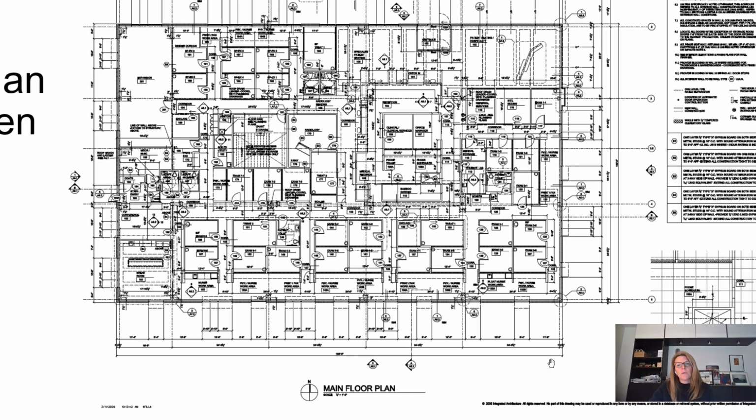Later on, we'll talk a little bit more about how dimensioning works, where you're dimensioning. Again, here are the openings in the first row of dimensions. The second row is larger, whether it's to the structural grid or to larger cumulative dimensions, and then the overall is the furthest one out. So it depends on if you're looking at it from the outside in. It's getting more specific as you work your way in from the dimensions.